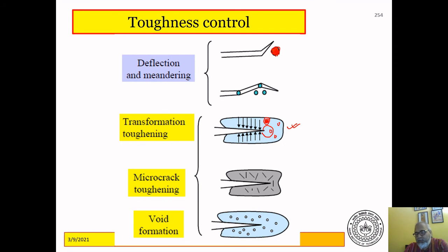Now imagine what will happen if I don't allow a single crack to form the new crack surfaces, but I distribute the crack surfaces that are formed. So instead of propagating this main crack, I have some mechanism by which I form micro cracks, many of them. Each of them adds to the delta A, and each of them consumes an energy Gc times delta A, and thereby reduces the overall energy of the system but protects the main crack from growing.